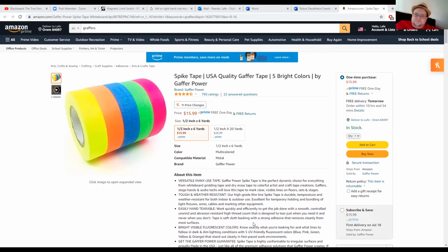So for this event, your robot will be placed essentially on a line of tiles. The idea is that you have a whole bunch of tape lines that your robot will run over. If you're using a color sensor, you're going to want it to point down toward the ground. If it's not straight down, you just want it to be in a way where the robot can read what's on the ground.